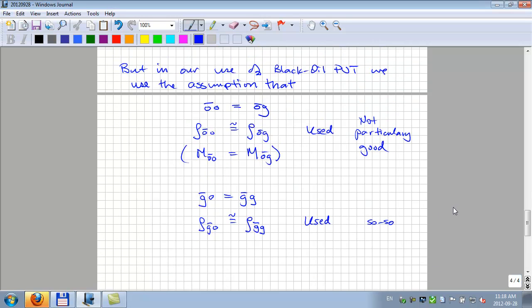Okay, so we finished last hour talking about the assumption in the black oil PVT model that the surface oil from the gas phase and the surface oil from the oil phase are assumed to be equivalent. In reality, the model is assuming that you can add surface oil from an oil phase and surface oil from a gas phase together, 1 cubic meter of each, and you get 2 cubic meters. That's correct. Okay, it doesn't matter what color they are. It's like diesel and gasoline.